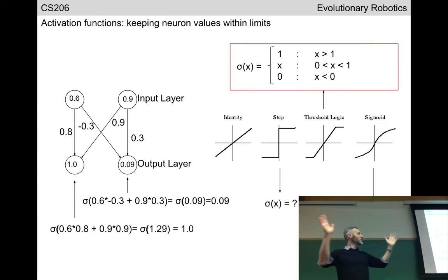Exactly. Another thing here is the example I gave you here. This is when we're squashing the value to between 0 and 1. But remember, we're really doing it from -1 to +1. It doesn't matter too much what the range is, because we're then going to scale that range back to the allowed range of motion of the motor. The point I want you to just take away from the activation functions for now is we're taking these raw sums and squashing them back to some desired range.